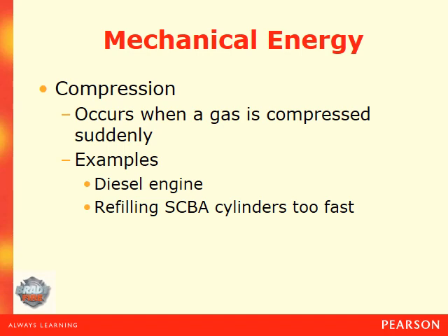Compression is another form of mechanical energy, and that occurs when a gas is compressed suddenly. Your examples are a diesel engine, or refilling an SCBA cylinder too fast. So that's kind of interesting. If you have your self-contained breathing apparatus that we talked about in the other chapter, and it's full of air, you put air in that cylinder and you do it quickly, it's going to get really hot. And that's because of the compression. Now, you breathe that air out really quick as well, and it's going to be an endothermic reaction, and it's going to turn it into ice cold.